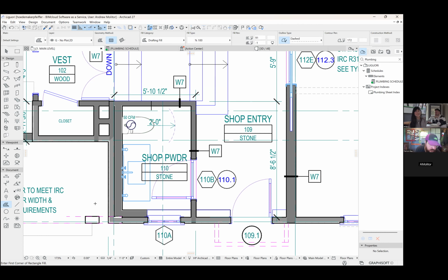Did it work? I know it seems weird, but hit Control Z and then Control Alt Z. Undo redo is a great way to select what you just placed, because sometimes you'll place something and it'll be hidden by other things. Okay, Control Z, then what? Then Control Alt Z. So just undo redo.